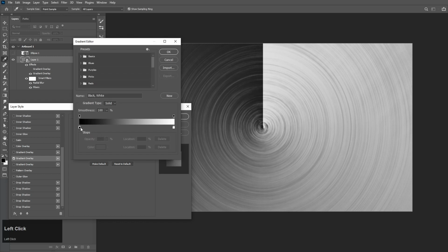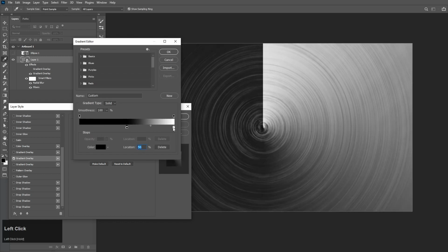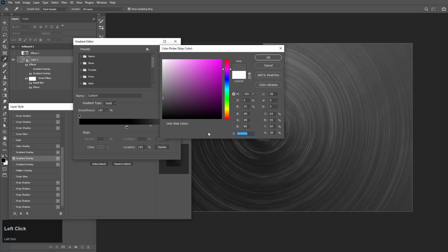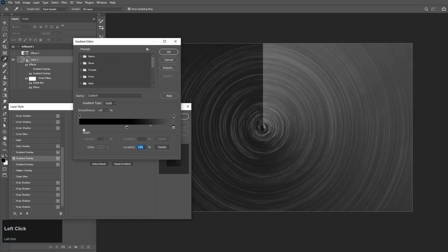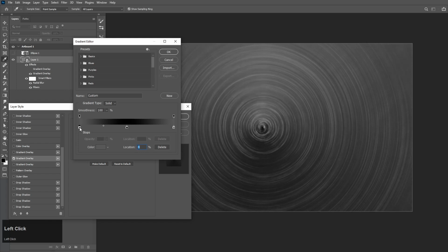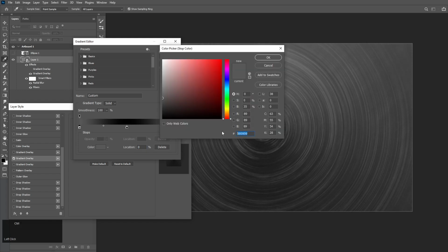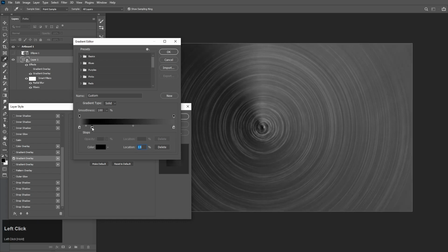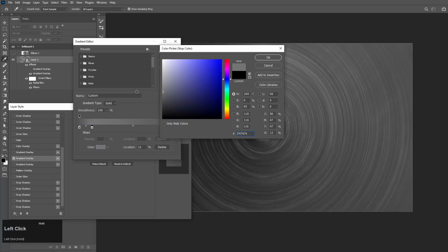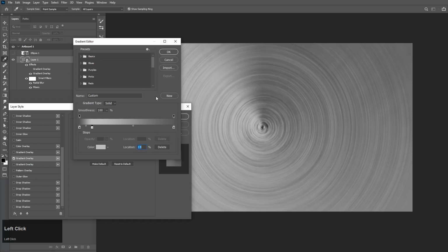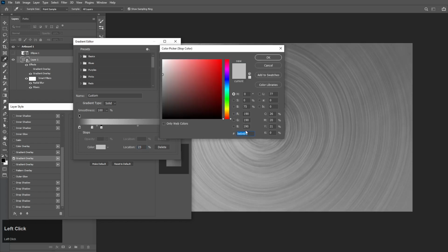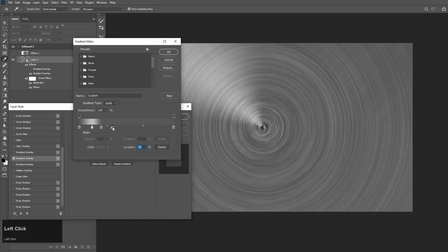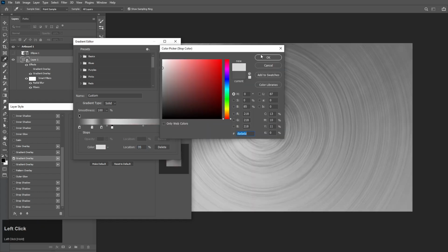If you double click this, you want to end and start with the same color. So I'm going to pick a gray. I'm going to copy that, and click on the gradient line to make another little node on there. I probably want to avoid pure black for this instance, but I'm going to just be like grays, lots of different grays, not quite white either.